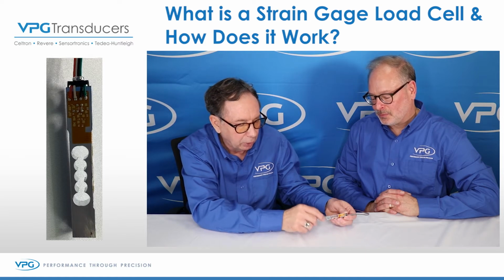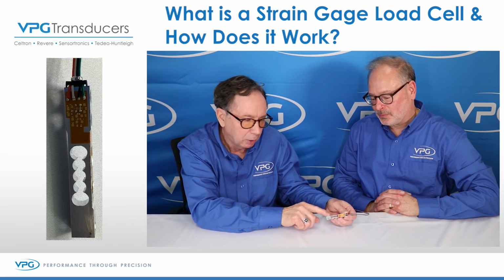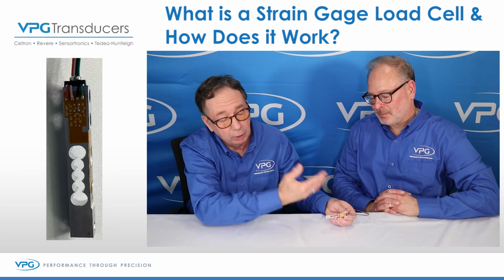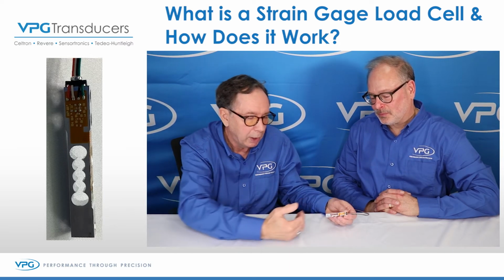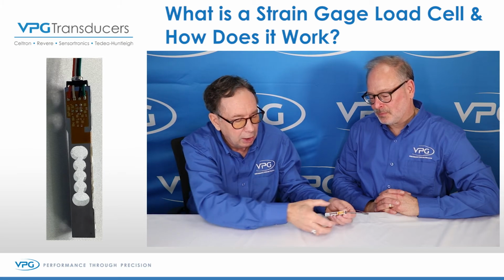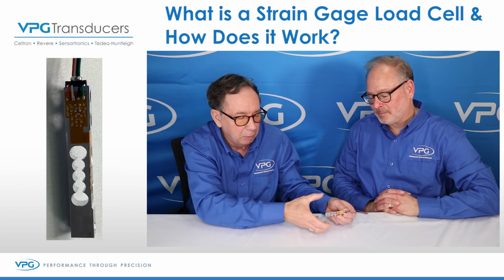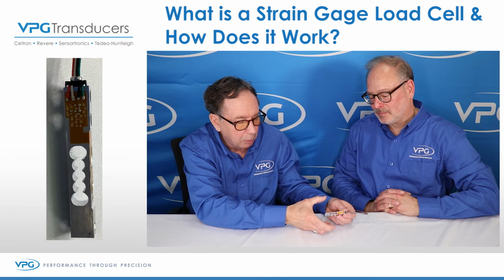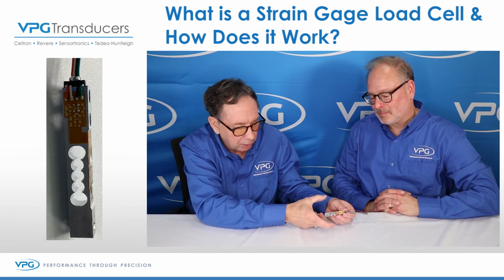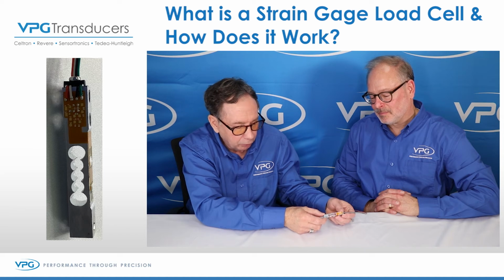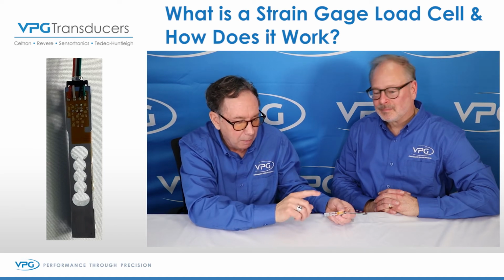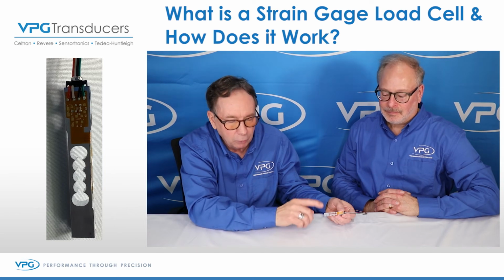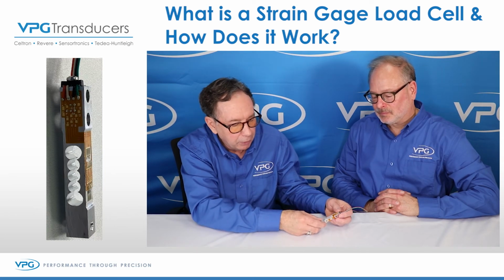What happens is because it's a mechanical beam, the load cell is a little resistant to bend on its way up, and it's a little resistant to return to its original form on the way down. So that center, it kind of forms a football shape in the middle of the performance parameter. So that's referred to as hysteresis, that center measurement. And then repeatability is, of course, repeating with the same given amount under the same given load over and over and over. This is a very small load cell.